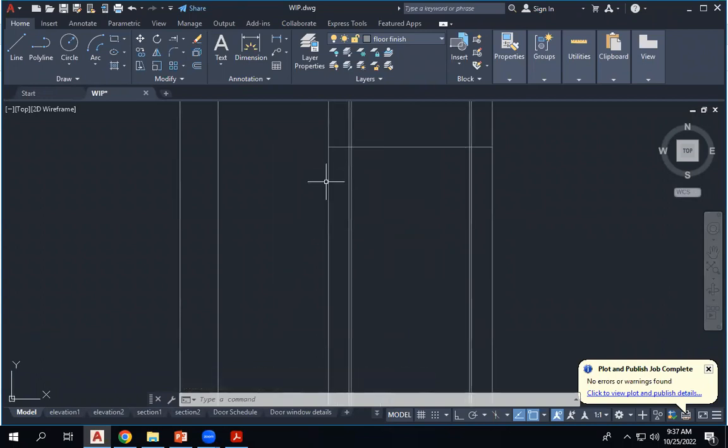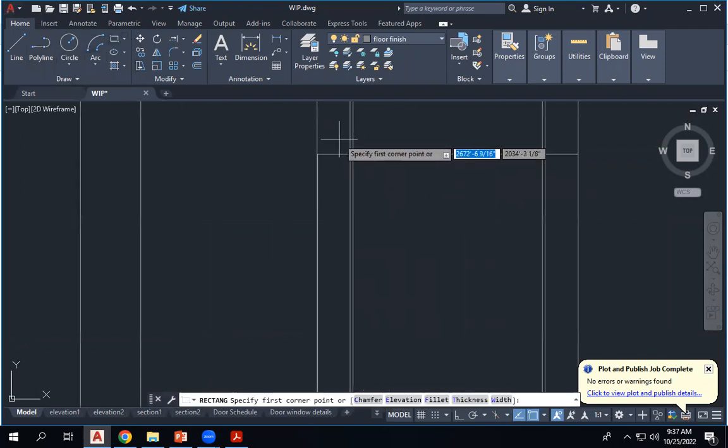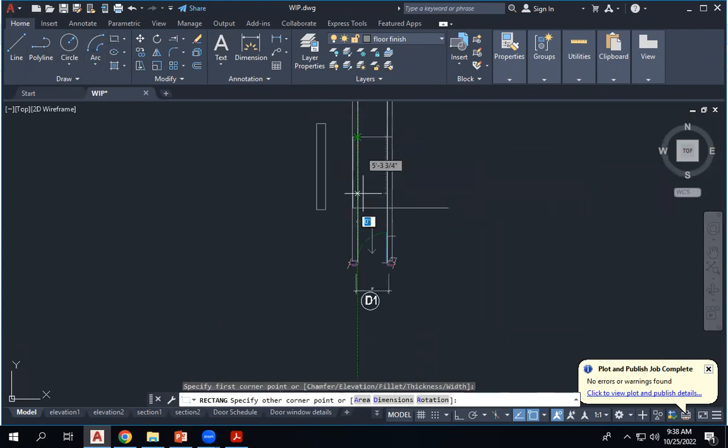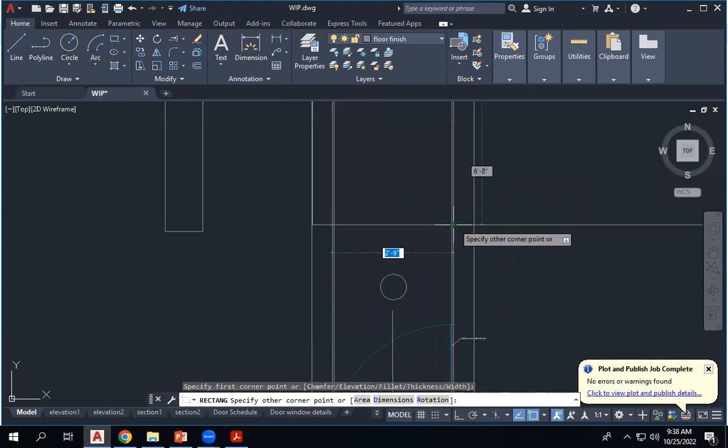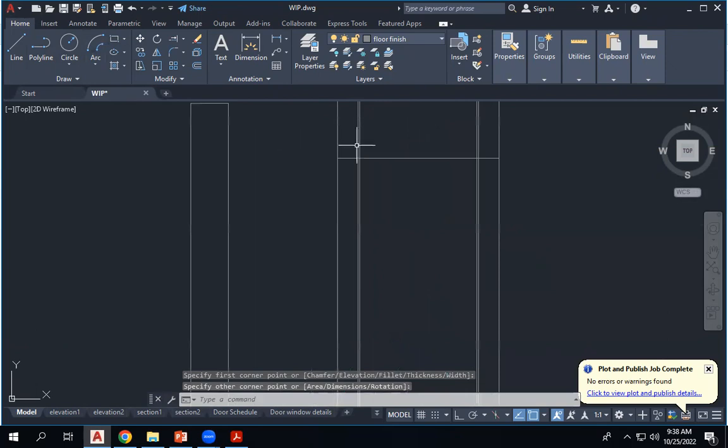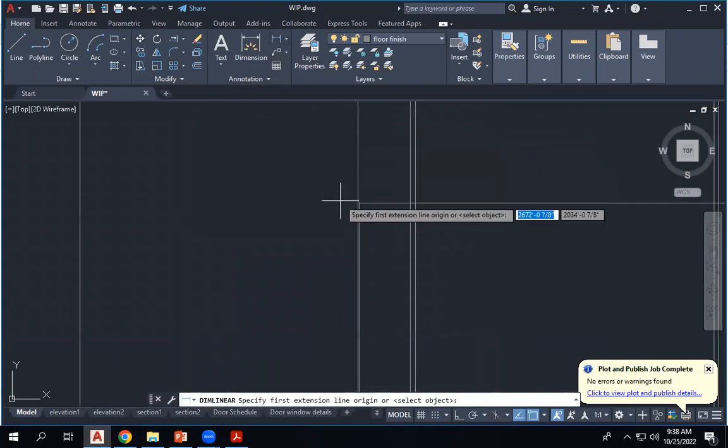The architrave, if you have the architrave going all around, so this will be the door size actually, from here to here. So you need to have another offset of the same width here to show that the architrave is going all around. So what I will do is I'll just get the dimension of this.